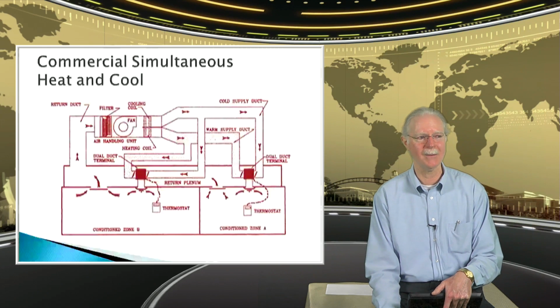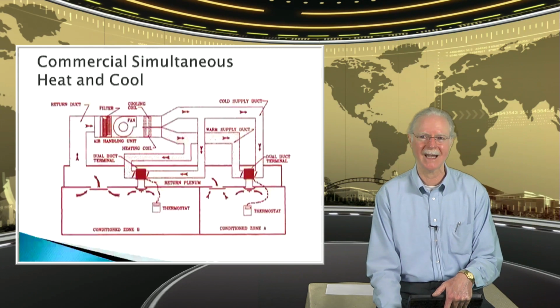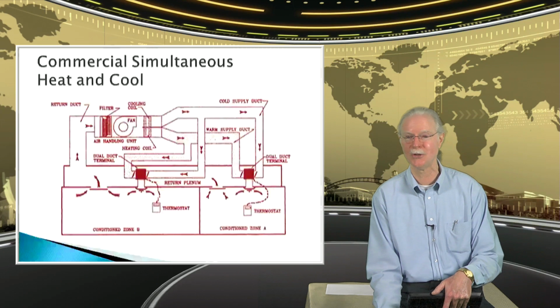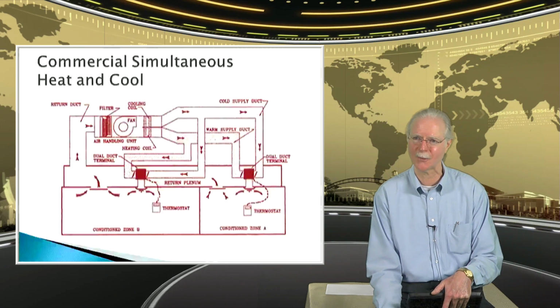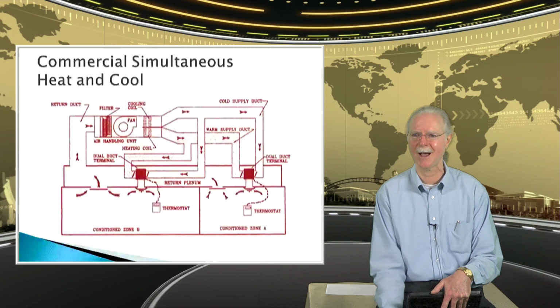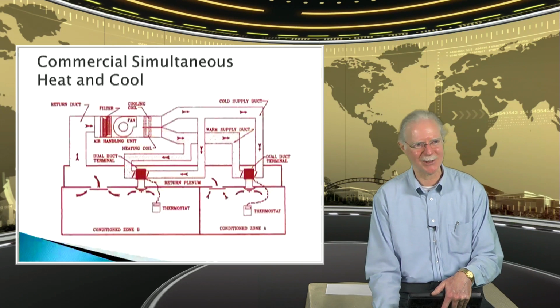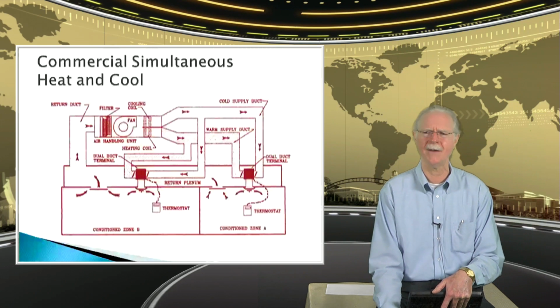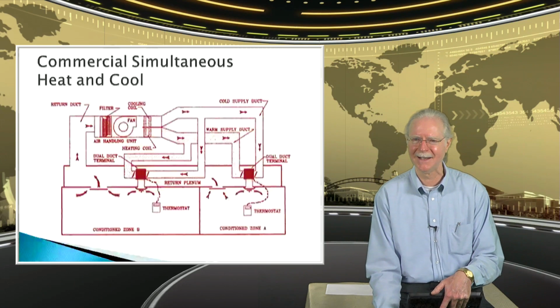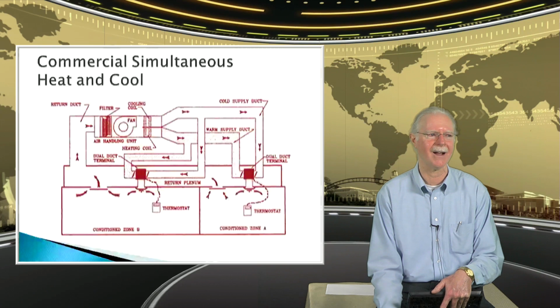Well, in the meantime, we've turned the thermostat all the way up, and now it will wildly overshoot until the occupant, who may now have gone to a meeting and won't be back for 2 hours, comes back to a sweltering hot office and now has to turn it the other direction. And their automatic reaction is, I'll turn it all the way down, that'll cool it off faster. So you can easily see how the occupant is really making this system crazy.